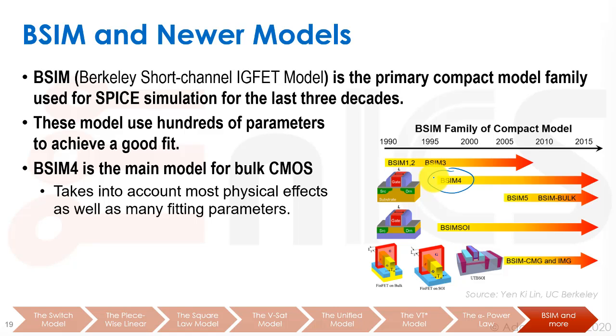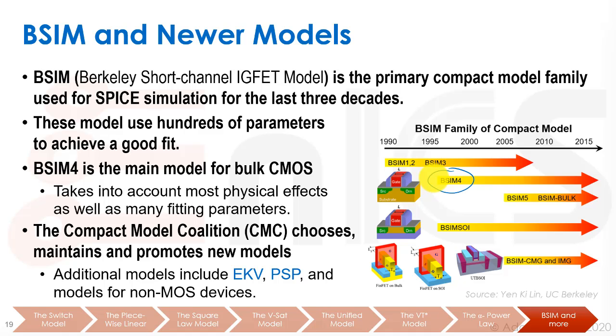So that's the main model for bulk CMOS, and it takes into account most of the physical effects as well as many fitting parameters. The Compact Model Coalition, the CMC, was started to maintain, promote, and choose new models, and maybe make a standardization of them. There are many other models from different groups. Berkeley doesn't have a monopoly on this. There's the EKV model, and the PSP model, and different models that try to show that they're better than the others and should become the industry standard run in SPICE or Spectre or whichever simulator you're using.